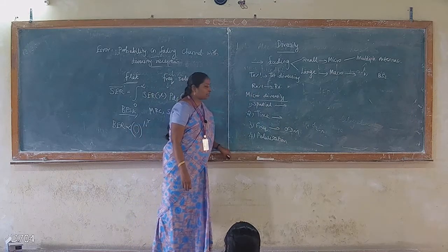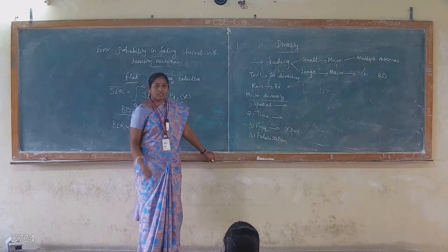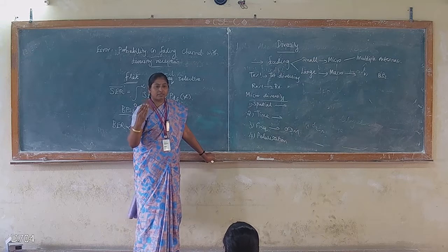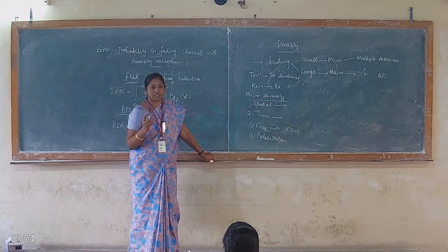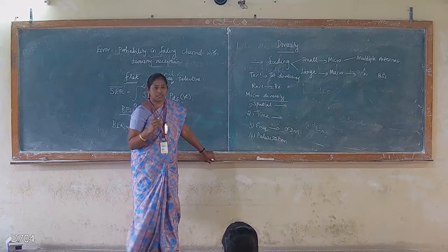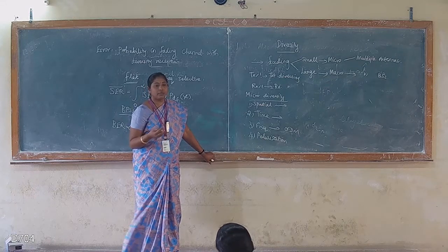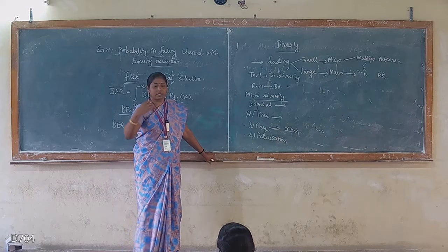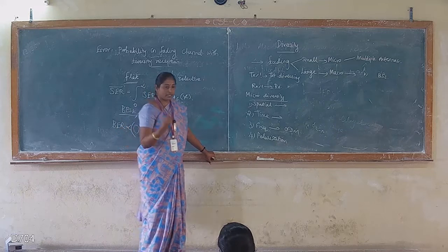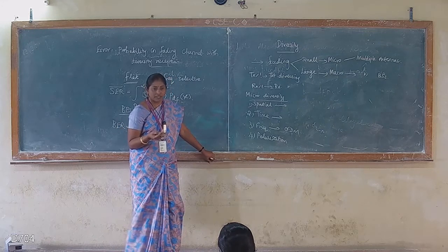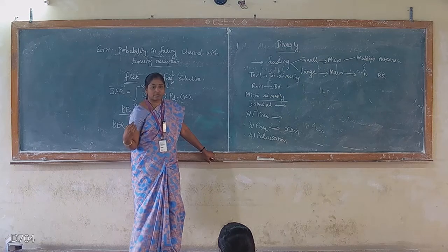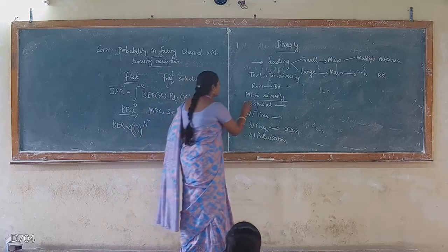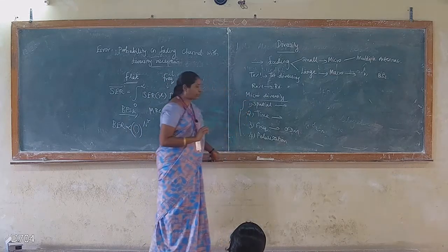Then polarization diversity, what we are doing? We have two polarizations, one is horizontal and the other vertical. Okay, so at the receiver we are using two dual polarized antennas to receive both the components, horizontal as well as vertical components. Then we are doing the analysis. Which antenna has the higher signal strength? So that antenna is connected to the receiver. Okay, we are receiving both the polarized waveforms at the receiver side, and the best copy is given to the receiver for further processing. So these four are the types of micro diversity.